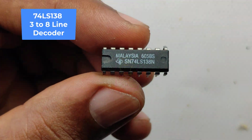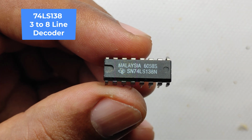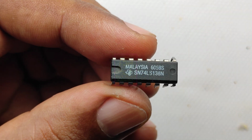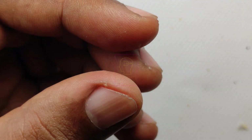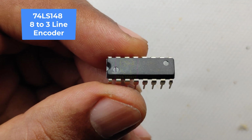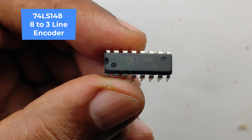This is 74138, which is a 3-line to 8-line decoder. This IC we will use in the receiver section. The IC has enable pin and with the help of that pin we can cascade one more decoder and switch 16 devices. This is 74148, which is an 8-line to 3-line encoder. We are using this IC in the transmitter section.